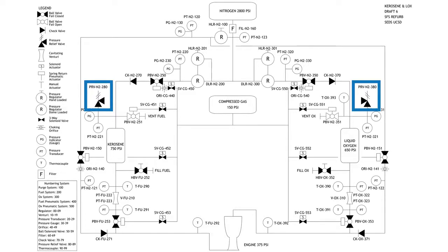One of the questions that the CubeSat team had, this is where this is coming from, is could you use a pressure relief valve for a tube? You absolutely could if you wanted to release pressure from that tube. But the thing is that our tubes are filled with liquid usually. And so if you were to kick open a pressure relief valve and it was liquid, you would have liquid spewing out of your system. And that's usually a combustible fluid. And so if that's happening, you're spraying a combustible mixture into the air. That's really dangerous.